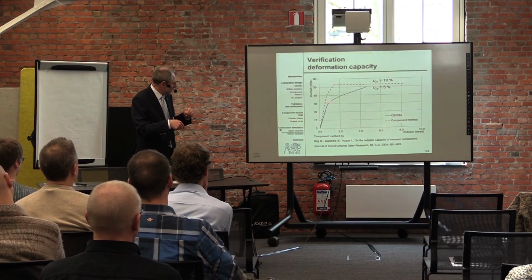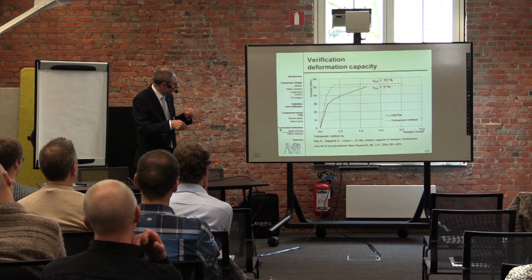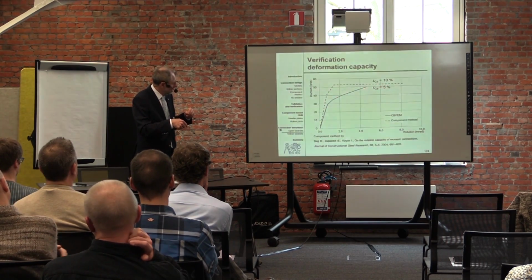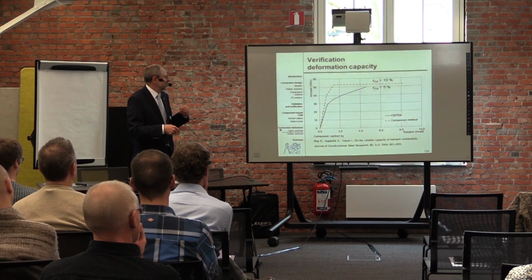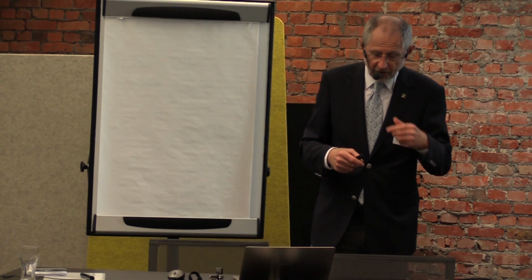If we use our model based on 5% strain, we are very conservative. But in our final stage, for seismic design, and also for those who will be interested in this with different material properties, we will introduce the 15%, the value which is in steel, without safety.